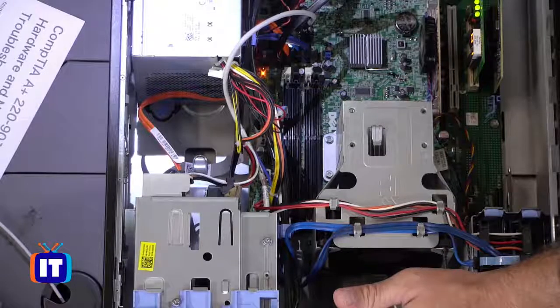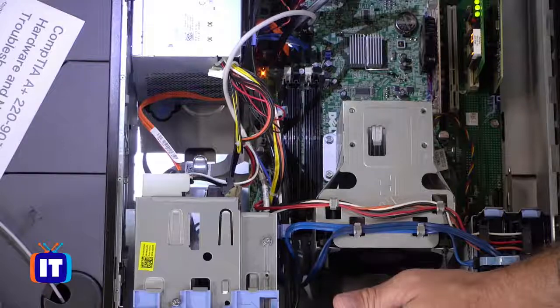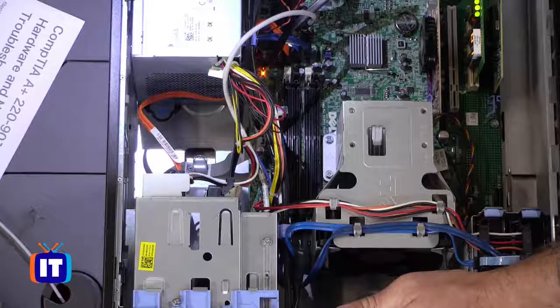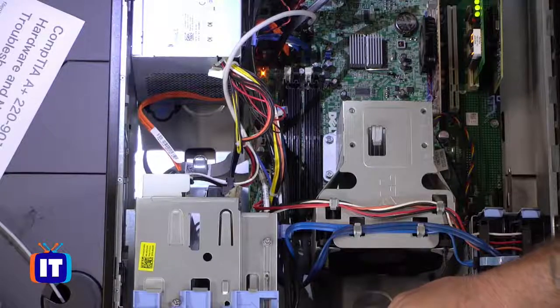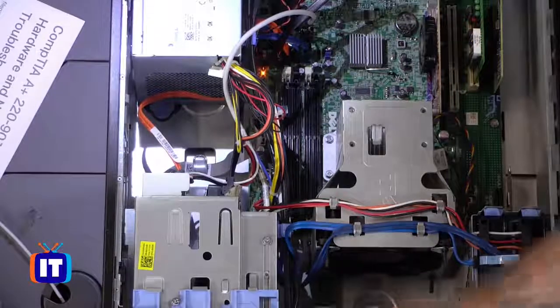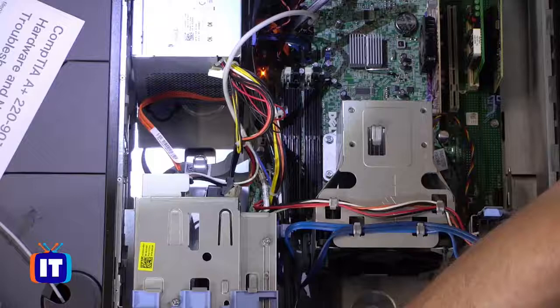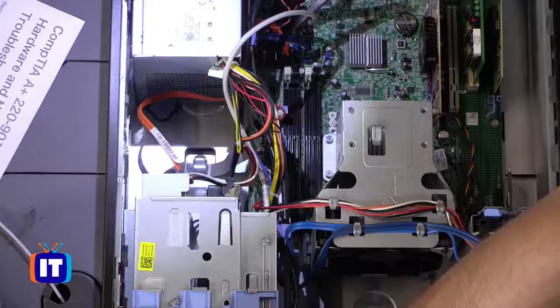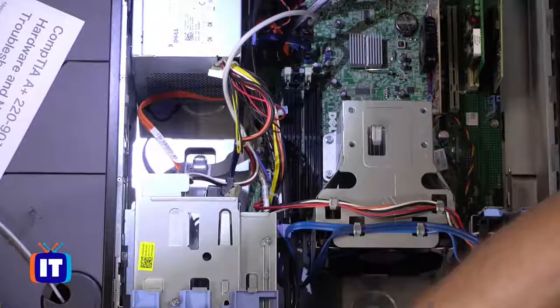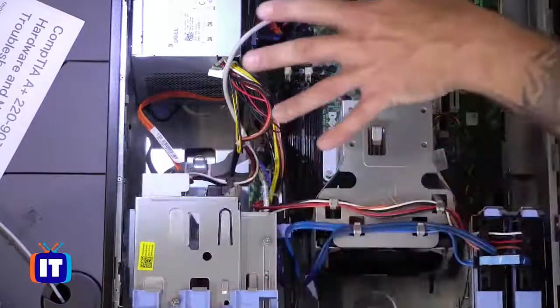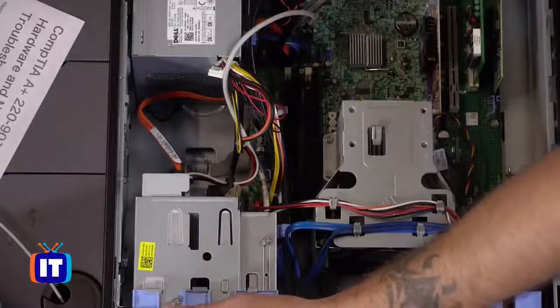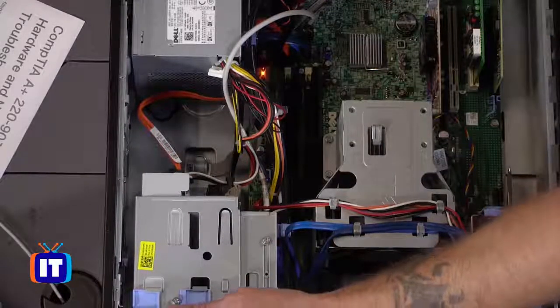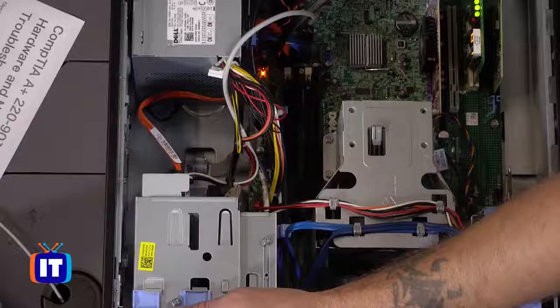Did you notice that it had some specific timings of that beep, right? That isn't like a metronome to your favorite, I don't know, blues song here. Yeah. Let's go ahead, and we're going to unplug that one more time, and I'm going to dissipate all the electrical current out of here by pressing the power button and holding it in. And notice that little light there just behind where Dan's shining that light. Notice how it dissipated and it went out. That lets me know there's not any residual electrical power on the motherboard. And we'll do this one more time. Yep.